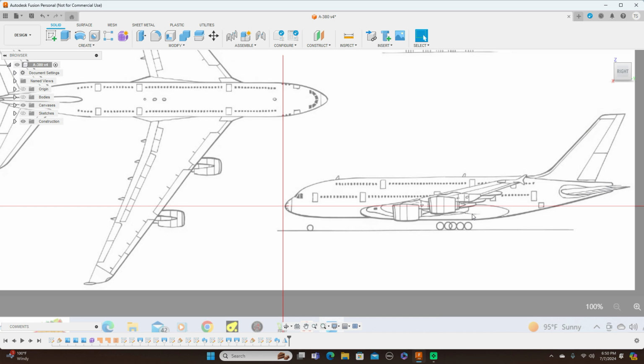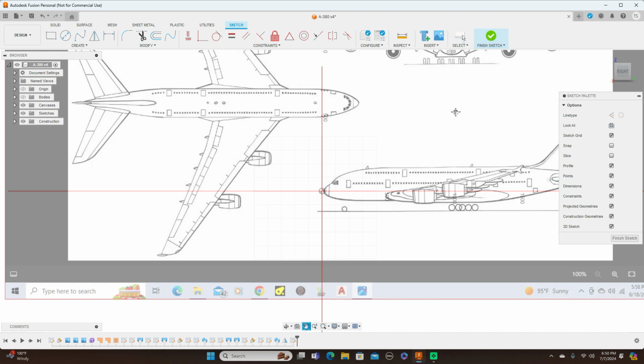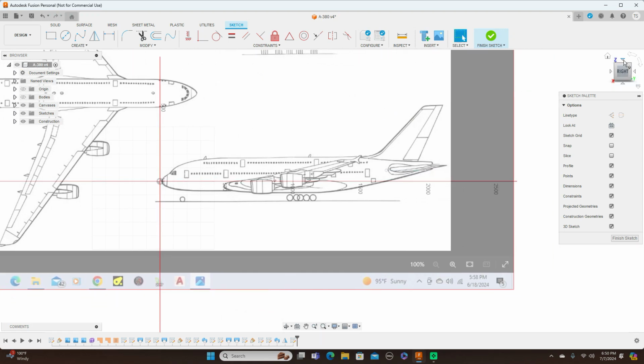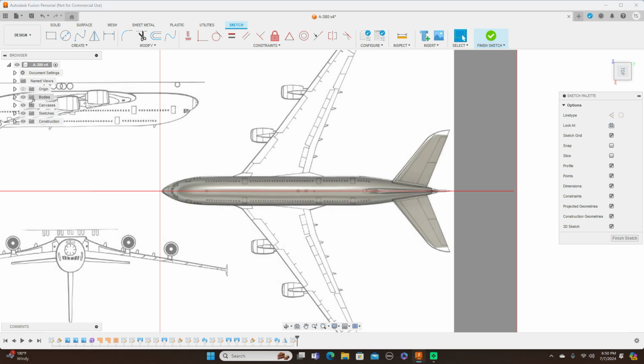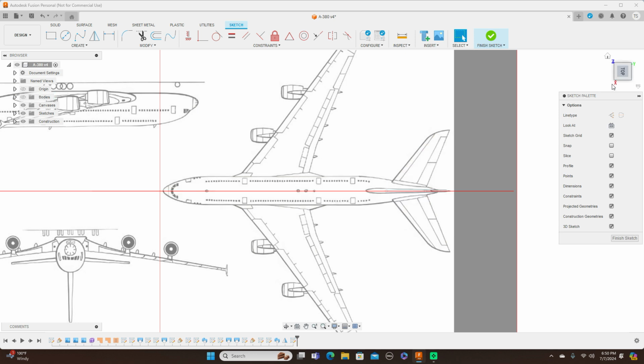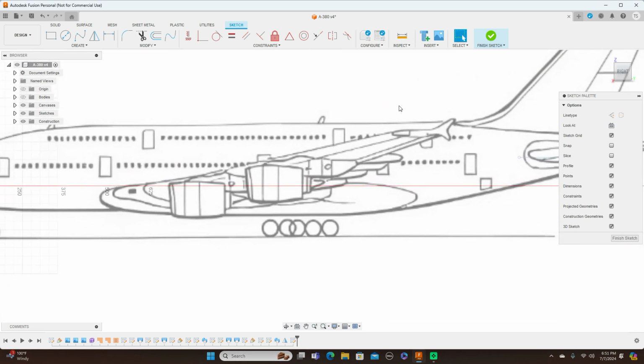So what I'm going to do is draw an arbitrary airfoil right through here. And to do that, we click Create Sketch on this plane here. And this is that middle plane. So let's say we have a top picture of this, and I turn the bodies back on. As you can see, this plane runs right down the center of here. Okay, I make this a little bigger.